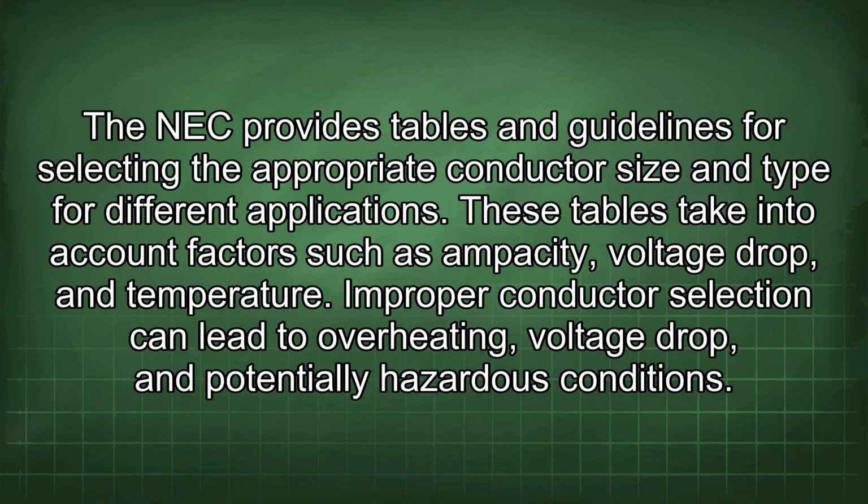The NEC provides tables and guidelines for selecting the appropriate conductor size and type for different applications. These tables take into account factors such as ampacity, voltage drop, and temperature. Improper conductor selection can lead to overheating, voltage drop, and potentially hazardous conditions.